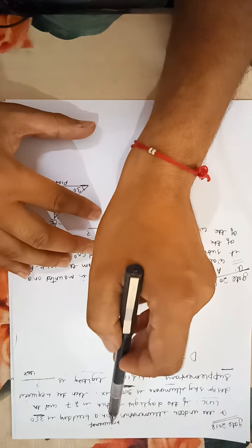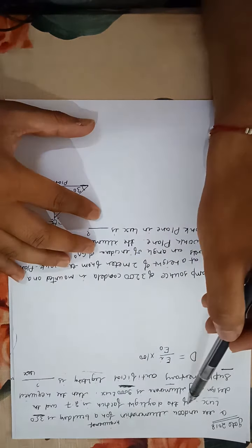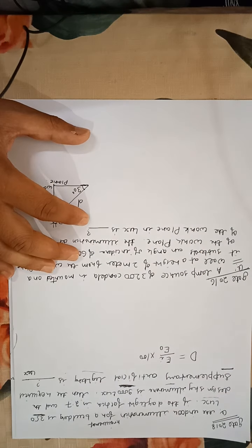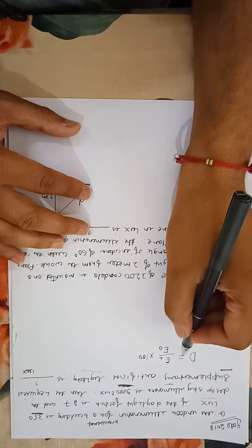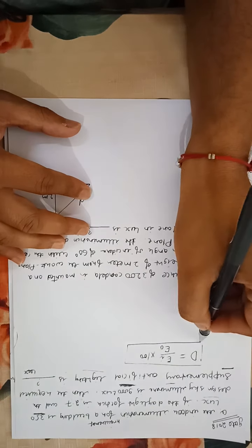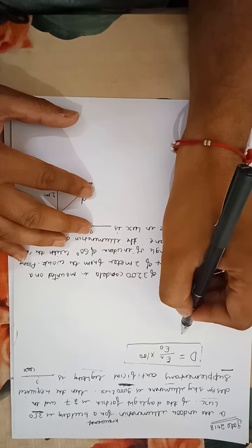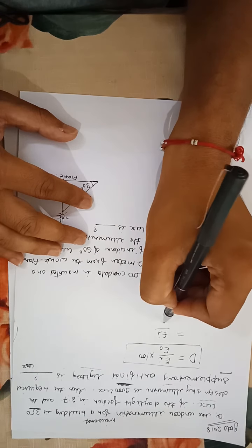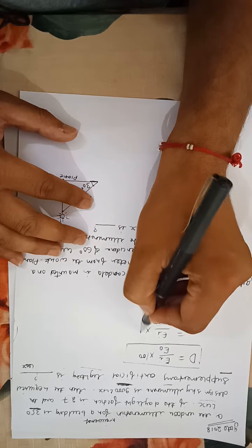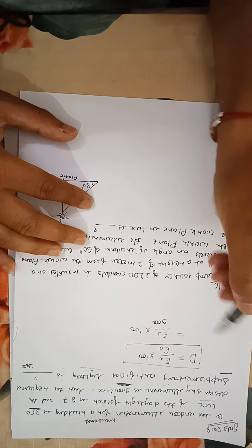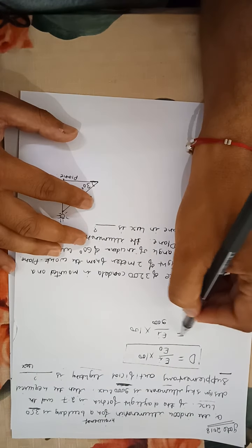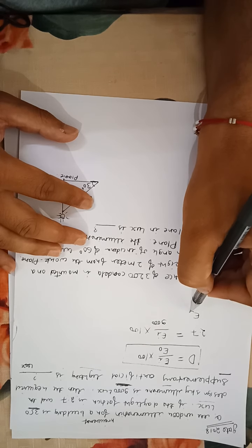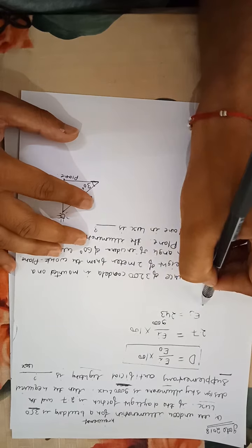Okay, the indoor illumination requirement for a building is 350. So we will do it now using the formula. EI is equal to E_outside into DF by 100. Outside it is 9000 into 100, and the daylight factor is given 2.7. So EI will be 243.